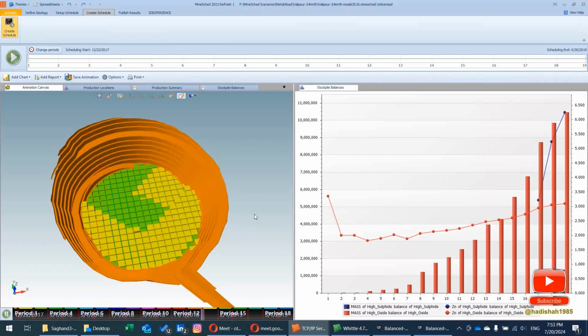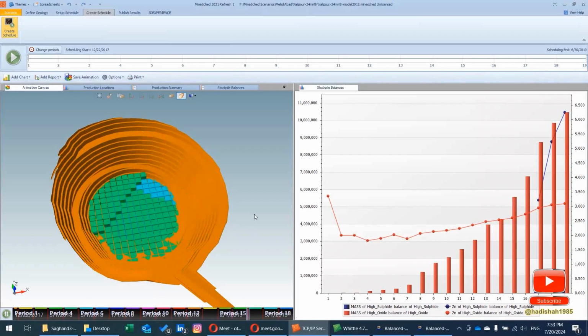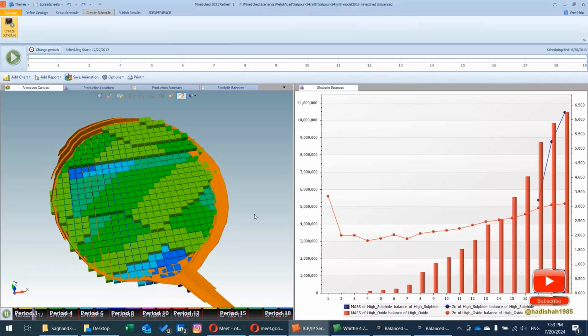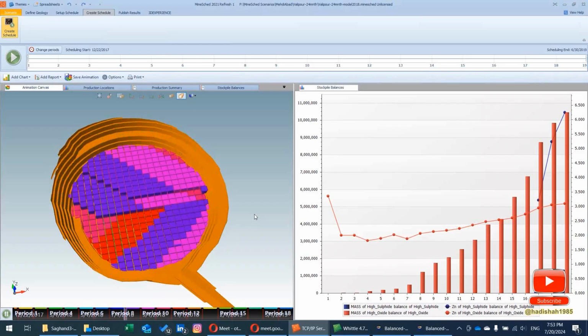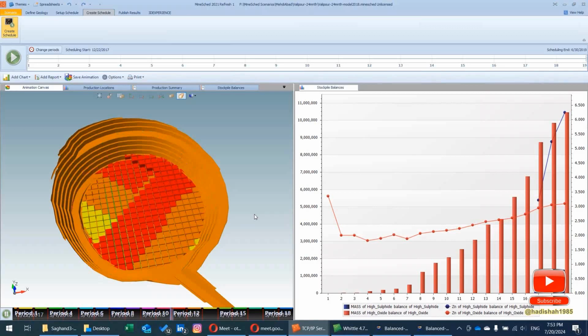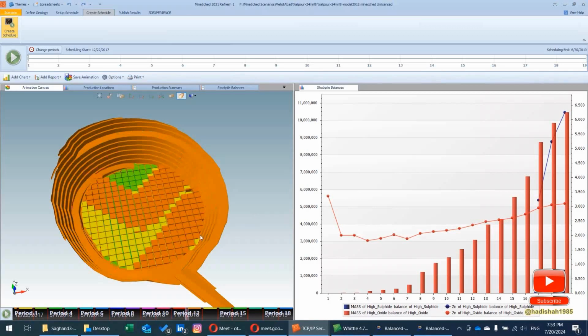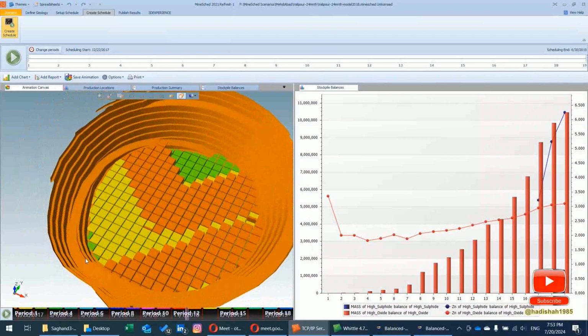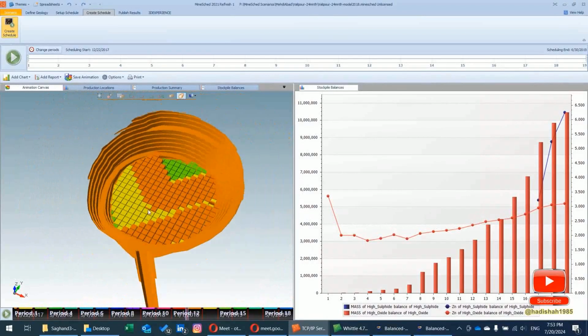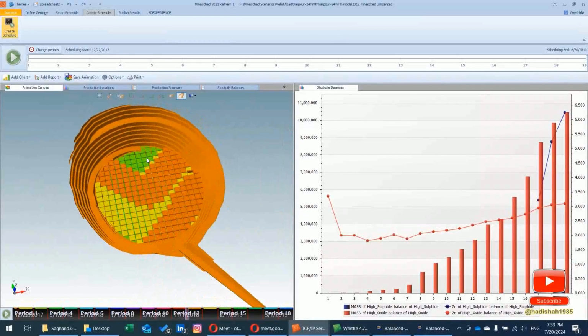This pit design only supports one ramping system that causes some concerns and risks to mine operations, in terms that when there is a difficulty or a problem arising in this ramping system, we have no other choice for pit exit, and the operation may be halted for several hours or several days.